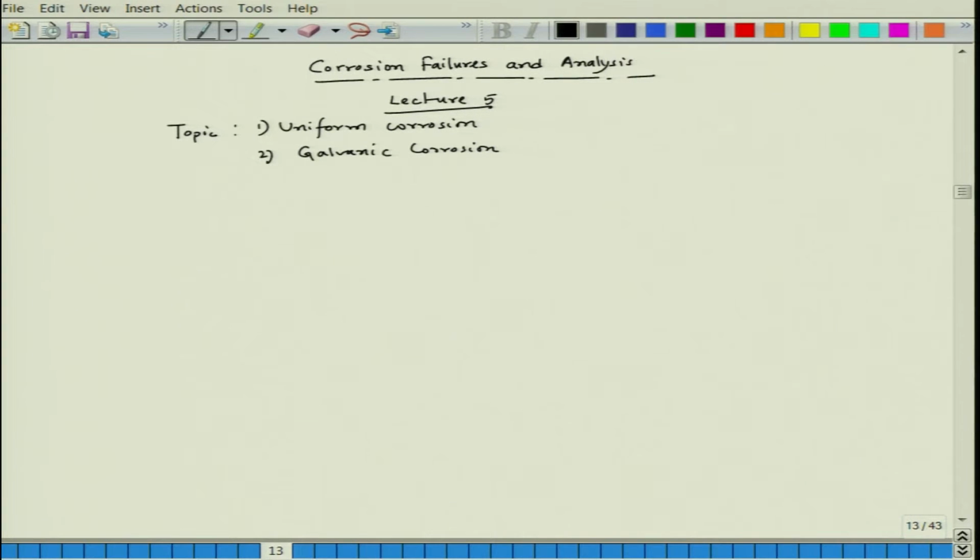So, if we recall what we have discussed in uniform corrosion, there are influences from different environments. It could be an SO2 or SO3 based environment, which prevails in petroleum refineries. There could be a situation of atmospheric corrosion where we have O2 as well as H2O moisture, and in that regard we have checked one situation like a rainwater droplet. If it stays on an iron surface, what sort of corrosion mechanism do we have,